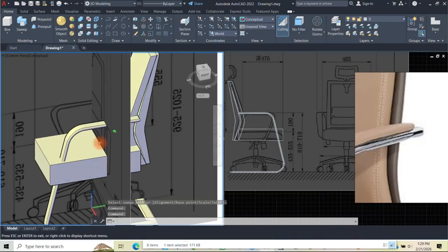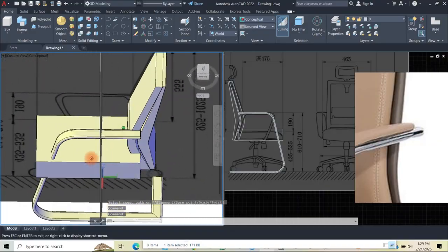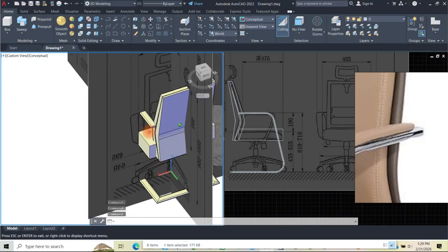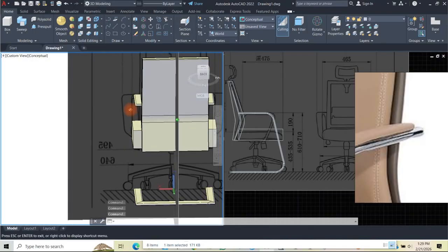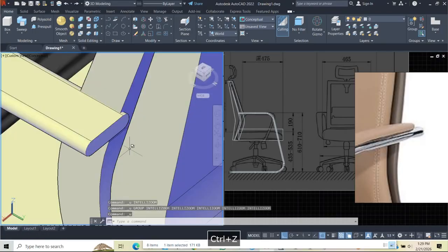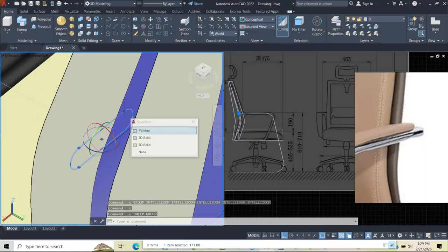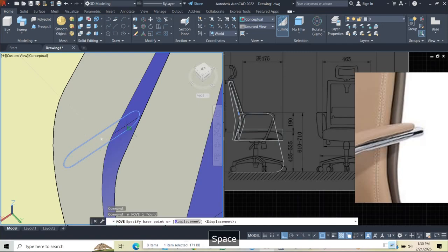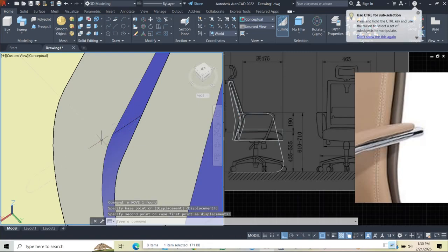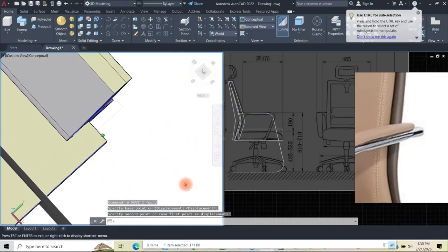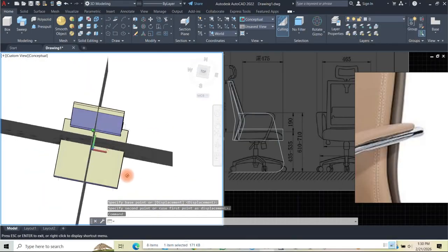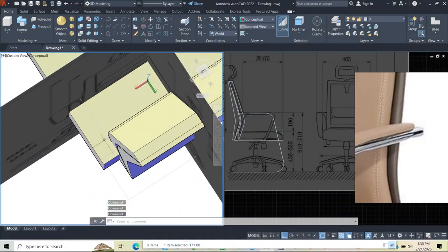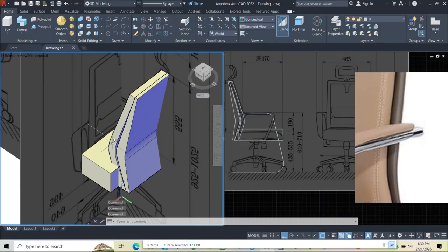So you see that this gives us this shape, and even though I forgot, I didn't take this thickness into consideration, so what I will do is undo that, and I will select this guy, and then I'll move it, M for move, pick from this end to this place, so that that will be outside. Okay, so let's see that. We can even move this backwards, but then let's just use this.